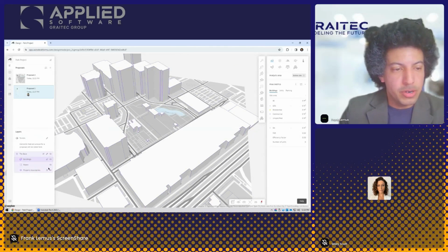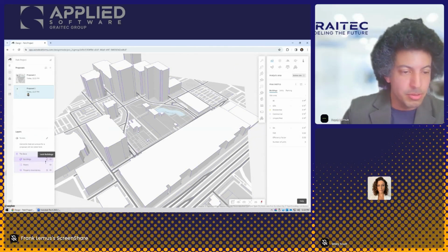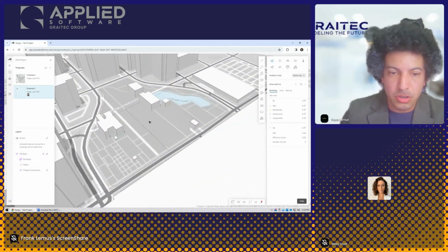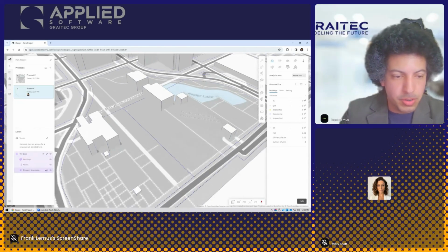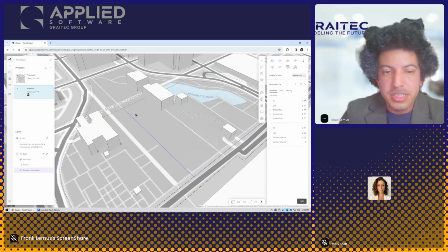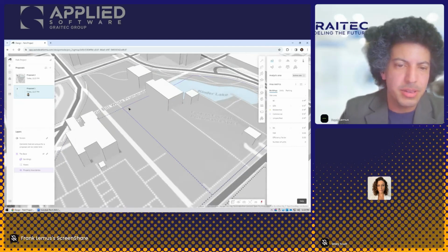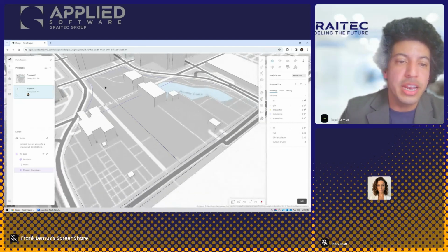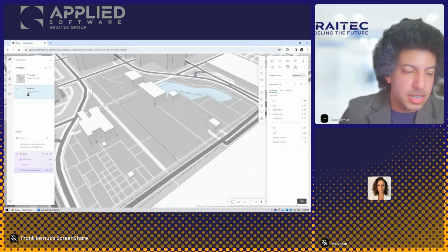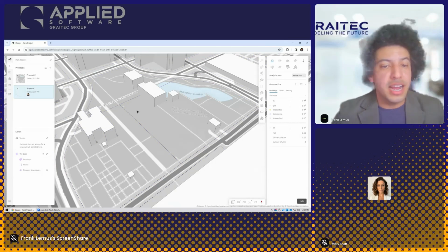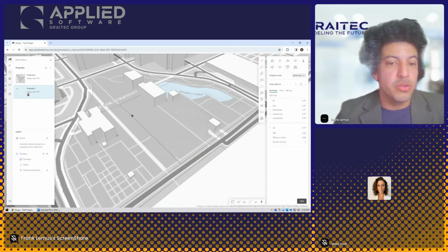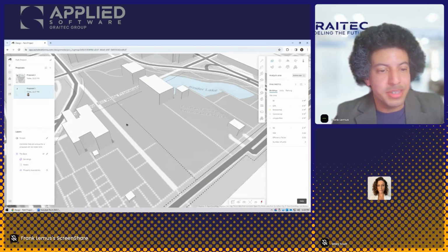So a couple of things about what we're looking at now that we have some content. The lock symbol simply means selection. So notice that if I hover over an area here, it's already locked. Okay. See how I'm hovering over the property boundaries? See how there's a purple magenta line, something like this? And as I hover over that area, it highlights. That's because it's unlocked. If I had checked it to where it's locked, I wouldn't be able to select it. And that's kind of what you want most of the time when you're working on your own geometry. You don't want to accidentally click and drag something because you can.